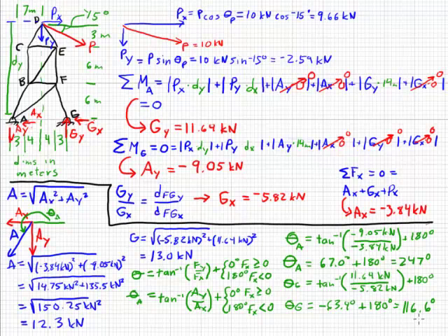In summary, we use a variety of techniques to start with finding the components of the forces that were applied in the first place, then using the moments about A to find our reaction in the y direction at G. Then we found our vertical reaction at A, summing the moments about point G. The advantage of doing that around these points is that many zero terms were developed.